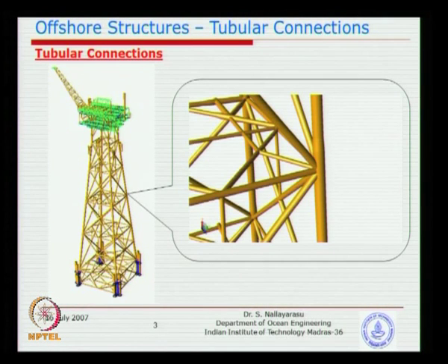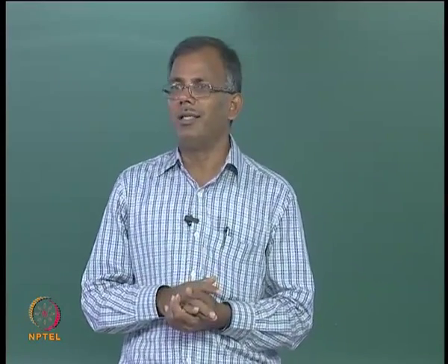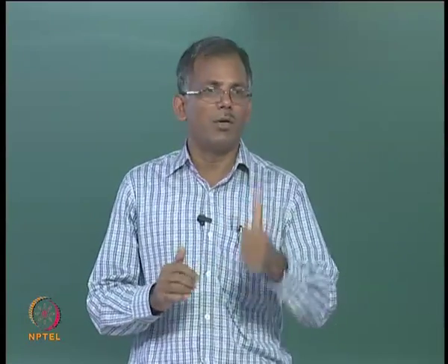So as you can see here, I think most of you are now familiar with the design of tubular members. Each one is carrying maybe axial, bending, shear, torsion and hydrostatic loads. All these loads are resisted by members, and we have decided to check the member from one end to the other at various close intervals, isn't it? Because design, as we discussed in the previous classes, means every section along the length must be safe enough to transmit the loads to this end and to the other end.